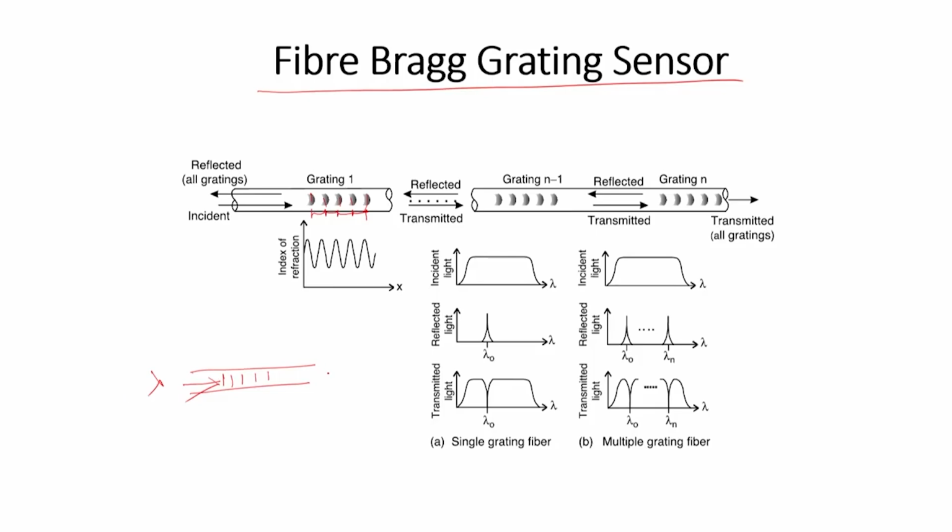But now, if I expand this system by the application of force, then this grating separation distance also expands, because this whole thing is flexible. So, this distance changes. As this distance changes, that will also correspondingly change the diffraction pattern. So, the diffraction pattern will then become a function, in a way, of the force that the system is subjected to.